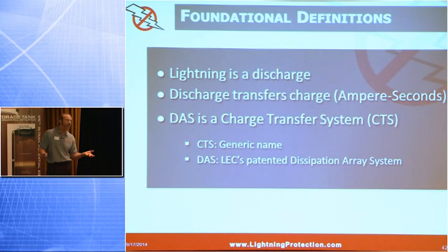An average storm cell lasts about 20 minutes. Now granted, you could have a couple of storms go through where you might have maybe an hour of storms, because there are different cells. But typically a storm cell lasts about 20 minutes. So you're discharging that site during the course of that 20, 30-minute time frame.